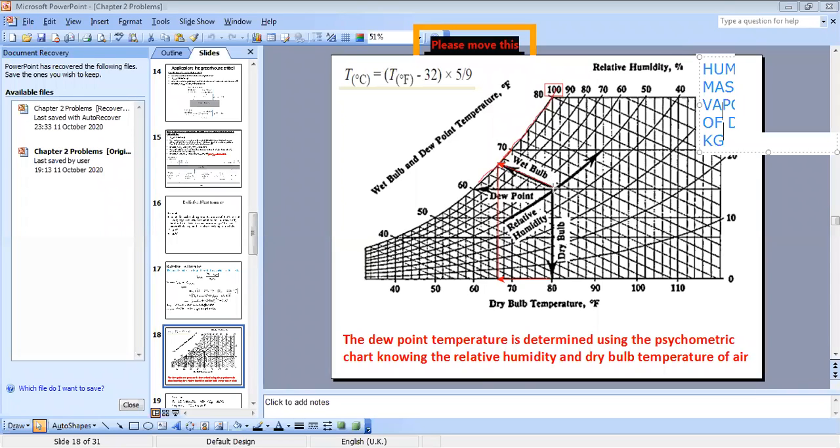Because look, if you want to see here, this is your initial point. If you go to this axis, this axis represents the mass of water vapor over the mass of air. As you can see, by going from point 1 to point 2, what is happening for the humidity ratio? The humidity ratio is increasing. So you are increasing the humidity ratio while you are decreasing the dry bulb temperature. So what is happening physically in this case? When you go along the line of wet bulb temperatures, then you have transfer. So if you want, when I move, I will write it here.